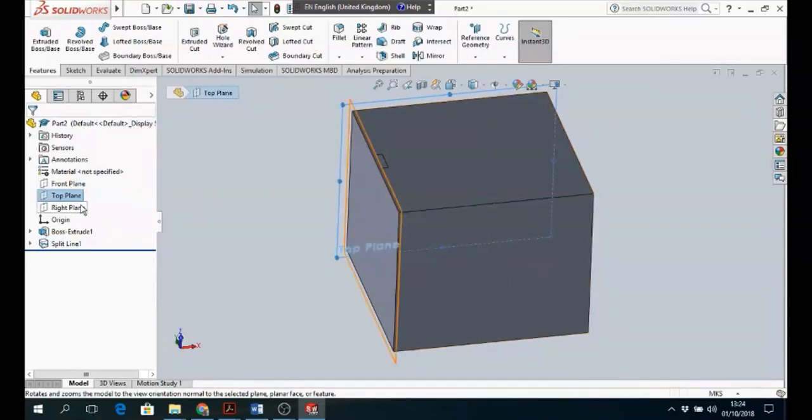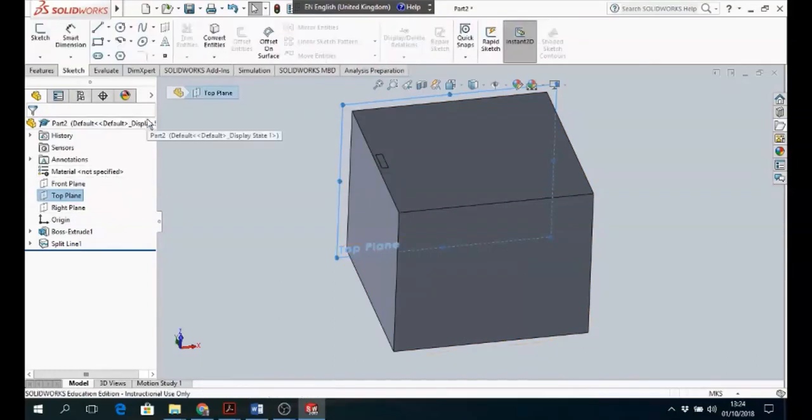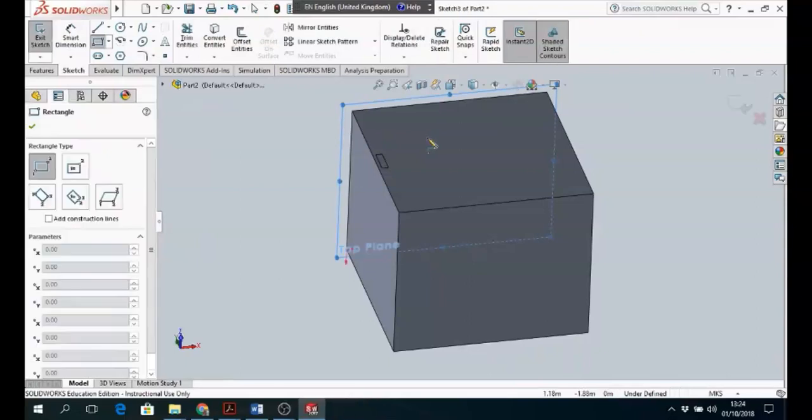It saves me having to create a new plane for that. So if we select one face here, we're going to do the window first, in around the middle of the plane here. Once again, we can set the dimensions as needs be.